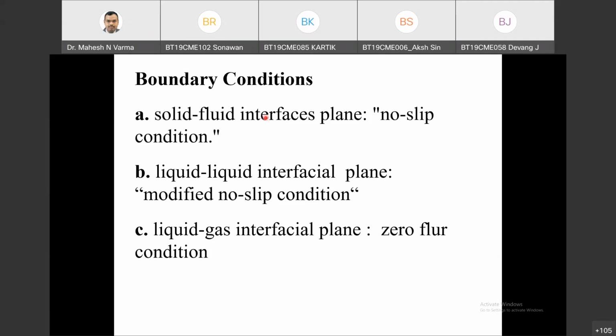Logically also you will come across this boundary condition, called a logical boundary condition. Everybody got this point? The gradient of velocity equals 0 at r equals 0, because r increases in both directions. From the center towards the wall, r increases and Vz decreases; velocity decreases from center to wall.